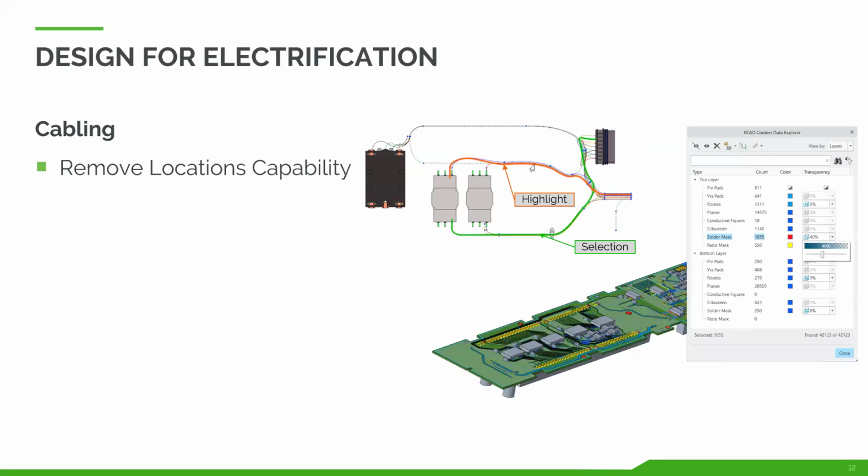Then on the side of cabling, we focused on cleaning up a lot of the cabling capabilities in Creo 11. First of all, we've modernized the remove location menu command. That used to have a really old menu, but we've now modernized it, added more options to it, like dynamic previews, better filtering, undo and redo support capabilities, and even for the cabling tree.